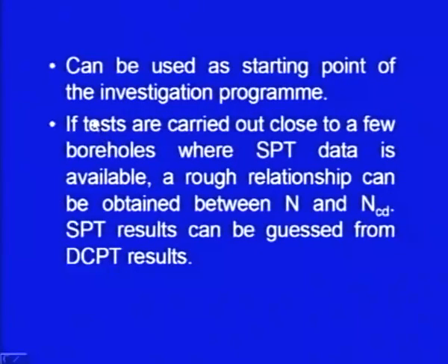Next advantage is that it can be used as starting point of the investigation program. In fact, we prefer it whenever we go to a site, instead of doing other tests, first we start with DCPTs. We plan some number of DCPTs, and the results of those DCPTs give you the idea of what kind of ground is there.